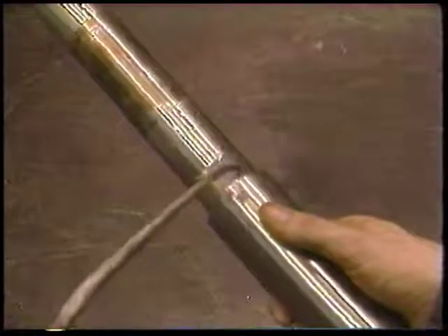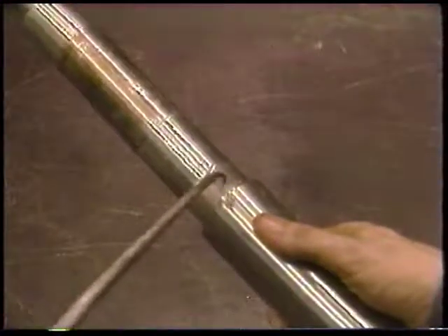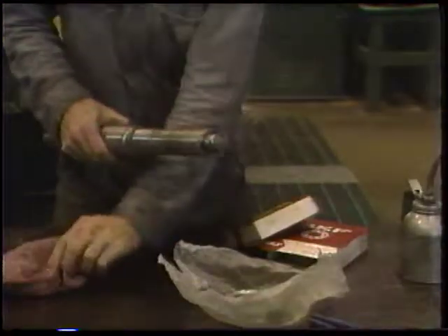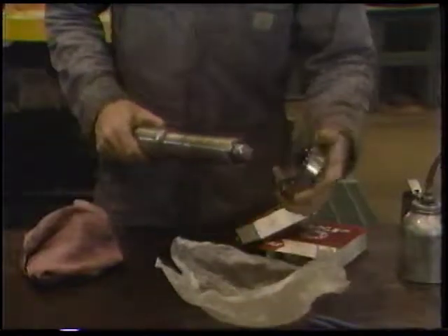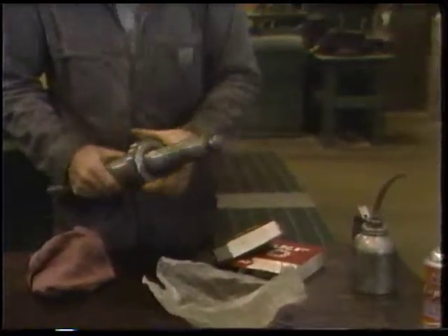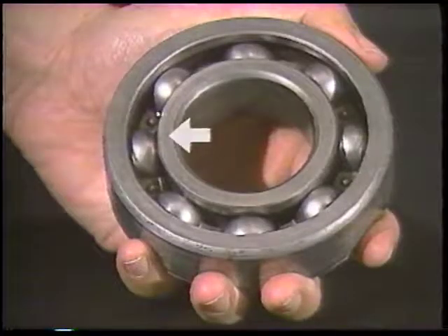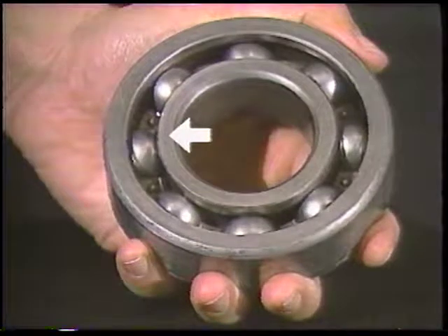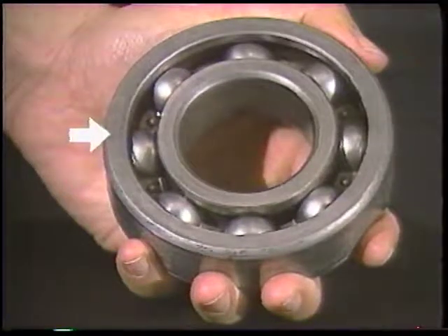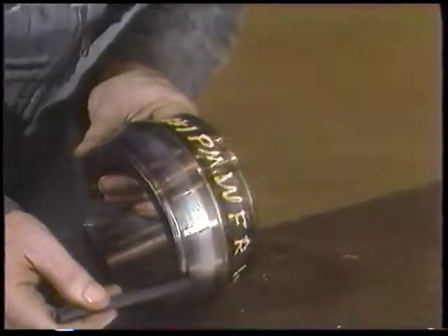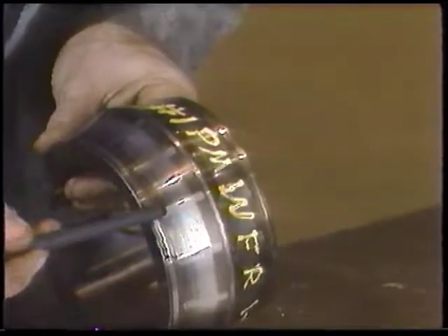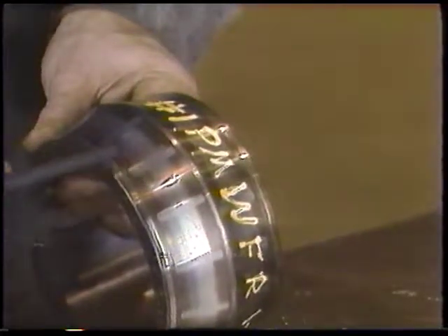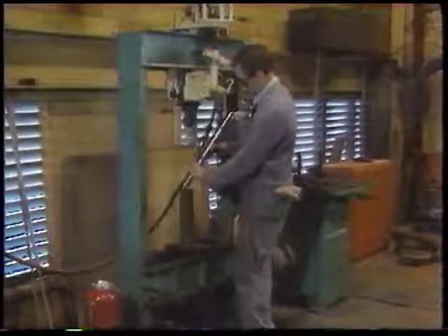When pressing a rolling element bearing into place, lubricate the parts to be pressed, then press with the right equipment. Press only on the ring being installed. For example, if you're installing a bearing on a shaft, press only on the inner ring. Do not press on the outer ring. And when pressing a bearing onto a bore, press only on the outer ring. If you do press on the wrong ring, the races and rollers are likely to be dented or brinelled by the force of the press.